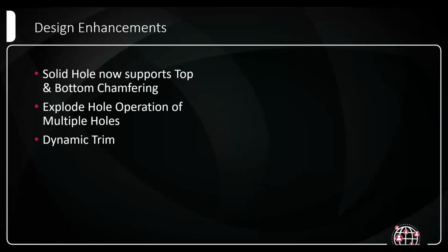Now, for those of you guys who've used Mastercam for quite a while, this is going to look very, very familiar. You're going to get a case of deja vu here. Years and years ago, we used to have a tool called trim, break, and extend. So basically, you have the trim to entities tool, the break tool, the extend/shorten tool, all basically under one roof. I want to say it was about 2020, 2021, they started breaking those functions out into their own separate options.